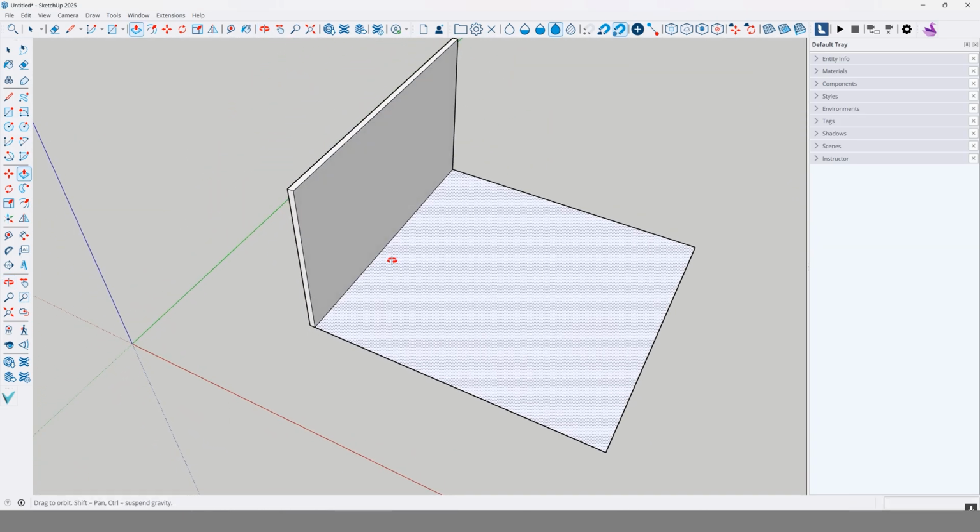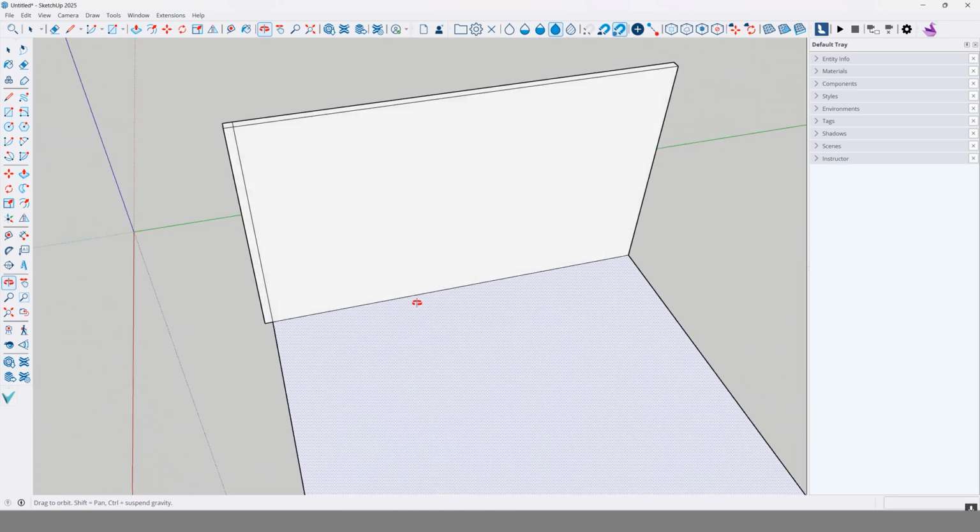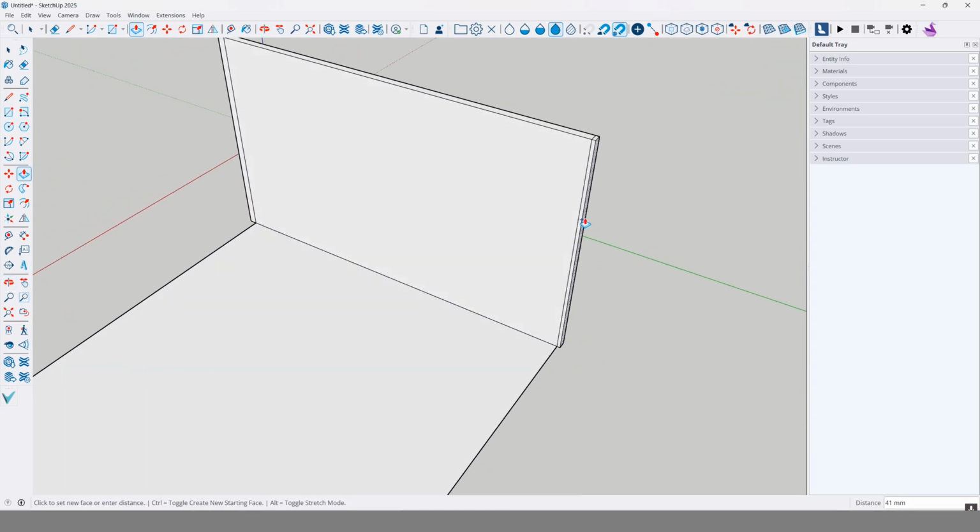Now to quickly create this as a whole room, you can now pull this wall out. Now at the moment it's pulling the wall out and extending it as a whole. If you want to just extend this and keep the existing lines, push Control just before and it will extend it, leaving the existing wall in place and showing you clearly what the existing length of that wall was. So we push Control, we extrude outwards, type 100. There we have a 100 wall coming out this way. We do the same here.